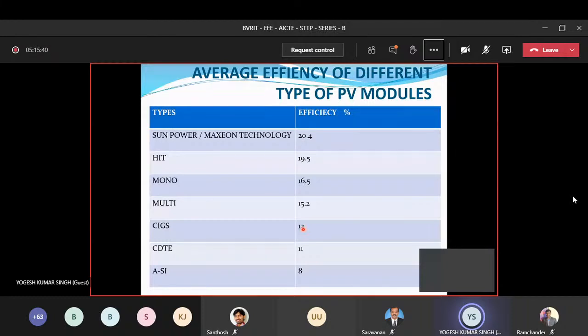Now when we talk about the performance ratio, because solar does not work all 365 days, it only works around 300 to 320 days. And in terms of insolation, it is around 4 to 7 kilowatt hours per square meter, meaning your module only receives 4 to 7 kilowatt hours per square meter of insolation in that area. So we discover a new parameter, called the performance ratio, and that is why the performance ratio is important to determine the system.